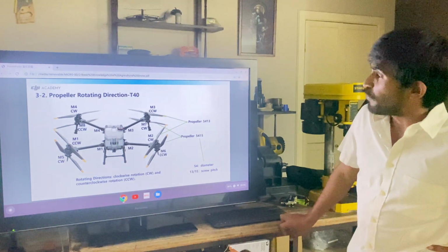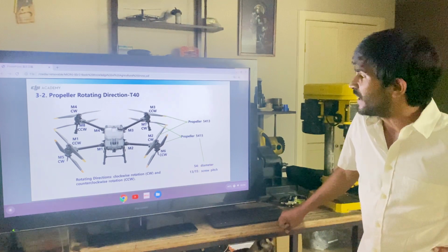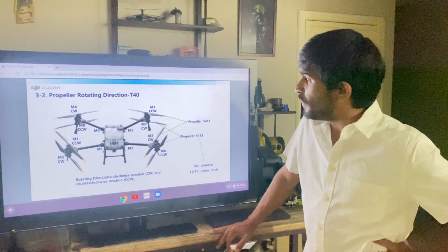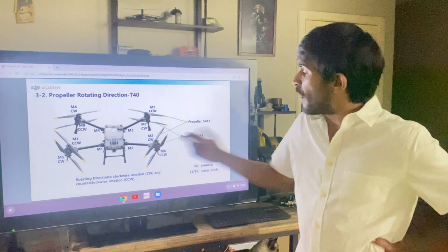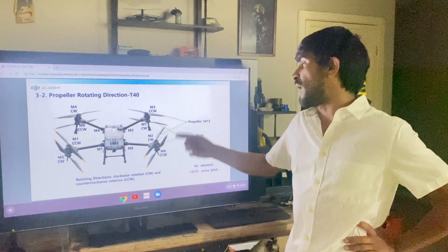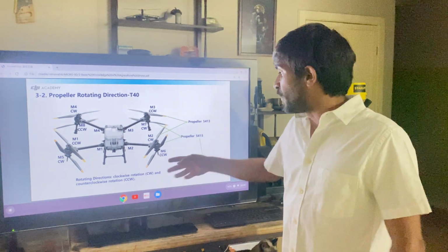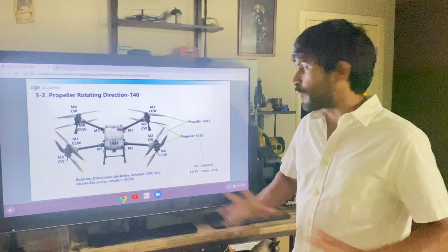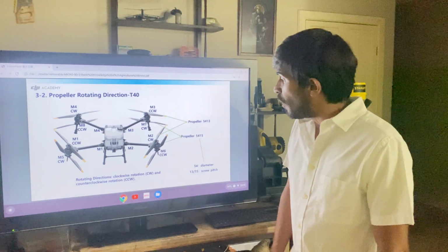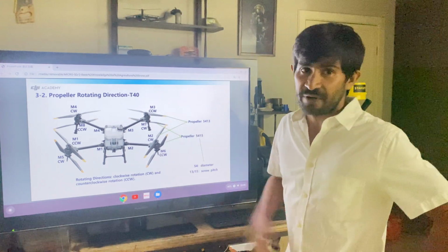All right, here we have a slide on the motors and their directions. This is quite a technical slide, but what you need to understand is that, unlike previous models, we have coaxial motors, with one motor on top, one motor on the bottom. That never happened before, but now we're doing it, and it's going to work great. You just have to be very careful about the directions in which they're installed. Always check while doing maintenance that the directions are correct.